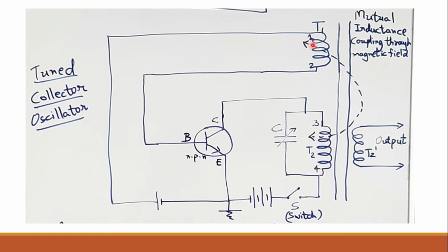So as the current will decrease over here, the same base current will decrease over here. As IB will become less, from the equation IC is equal to beta IB, again IC will become less, again less current is linked to this coil, and again IB will decrease, and this cycle will continue until which point?